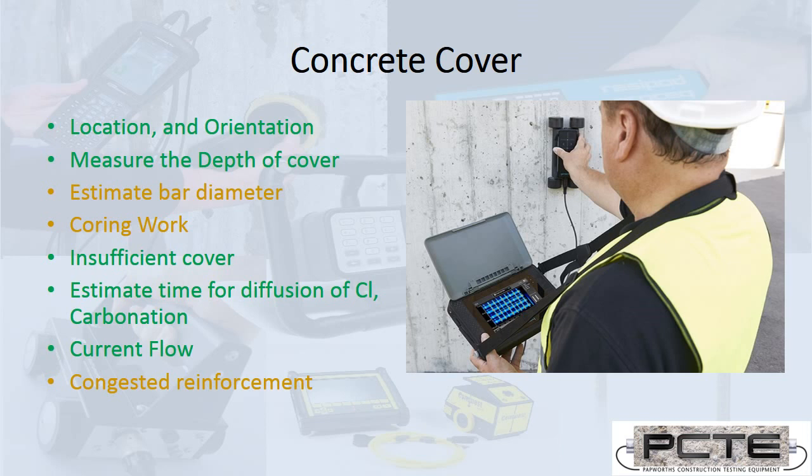The bar diameter is an estimate. It says it in the standard, and that's true in the world too. It's critical to locate bars separate from other reinforcing, and then the cover meters will give a reasonable result, but it really should be confirmed by destructive testing.